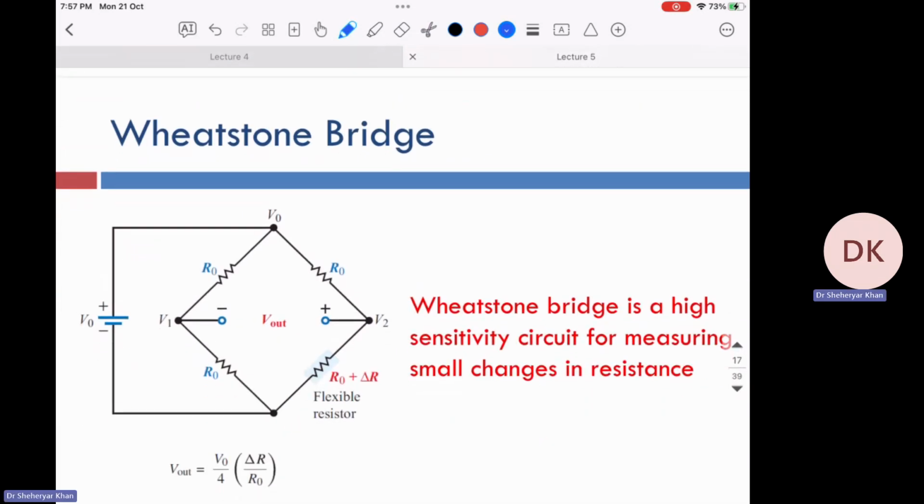So the next question is how to transform it. So force gives a change in resistance. Now change resistance into voltage, right? So you connect a voltage source into a Wheatstone bridge and connect your output here, right? So what happens is, without any disturbances in the arm, if all these four resistors are the same, there's no voltage here.